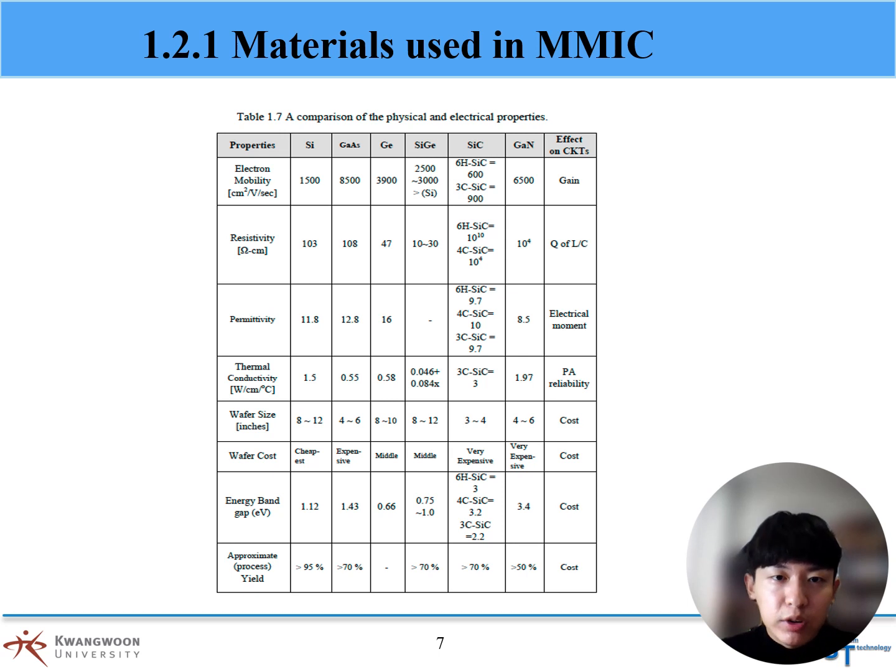Si is the most popular substrate material for chip manufacturing. It has high strength and an excellent passivation layer, resulting in high yield and low cost devices. GaAs is a high-speed substrate material for semiconductor chips. It is suitable for microwave components, enabling applications at frequencies exceeding 25 GHz.